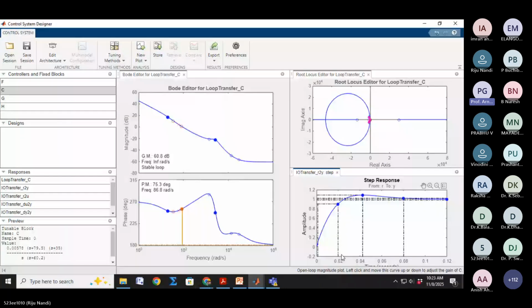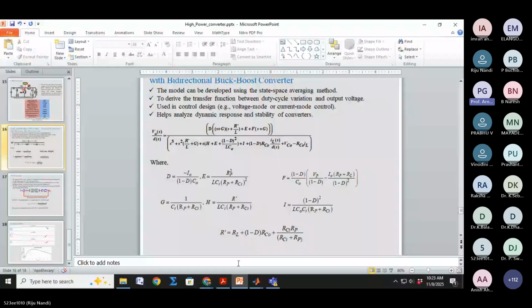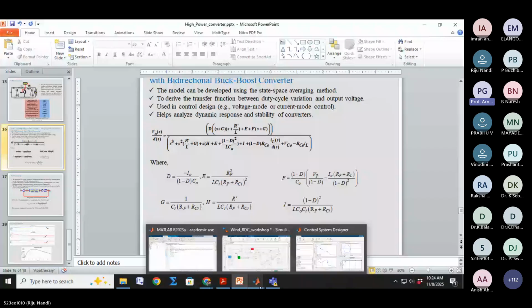You need not do all those state space modeling and other things, because if you have the differential equations and the state variables, we can directly design the sliding surface. Or if you want to design another kind of robust controller, in that case small signal modeling is not so important. Here it is done to convert the nonlinear converter to a linear plant transfer function of the converter. Then we can design the classical controller. This is the basic platform of the studies.